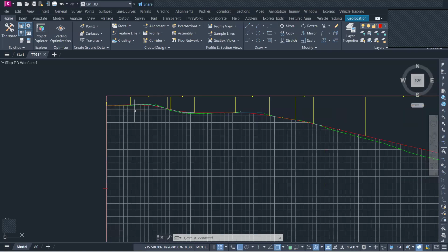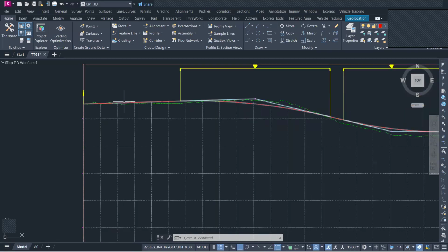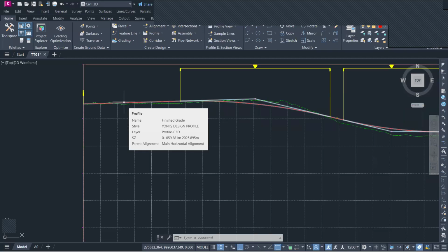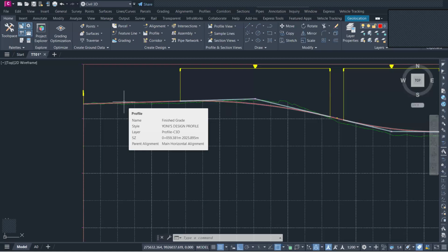This is how you approach it. The first thing is you will go down to 0.6 meters. And then once you go to your 0.6 meters, you will generate your report at that point. So you will save that report, the quantity cut and fill report, separately. Quantity takeoff is multi-step and it is scenario based. It will be changing with the scenarios that you have on site. So don't have a fixed mind on how you approach this scenario.